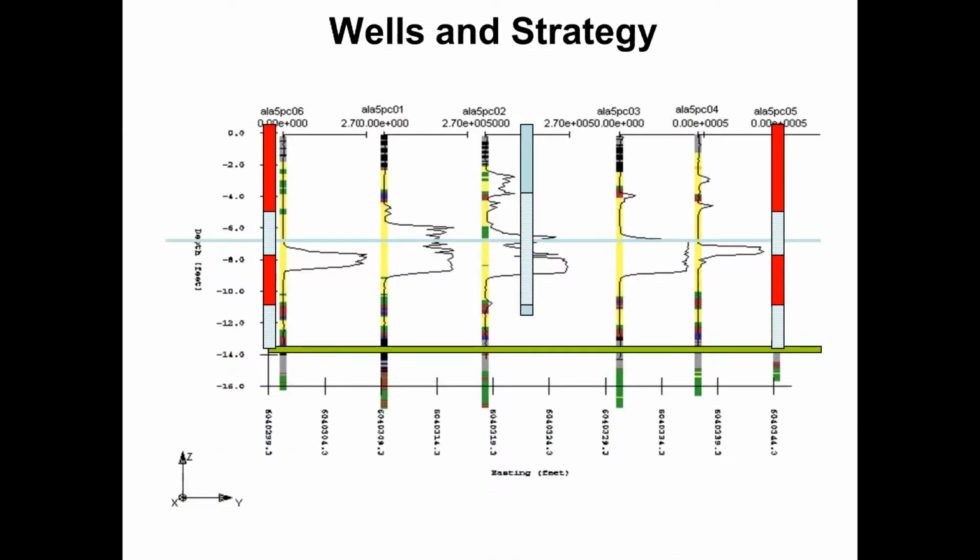That was the approach. And real quick, in a cross section, you see those profiles. Those are laser-induced fluorescence profiles, and they indicate where the hydrocarbon signature was strong when we push down in the middle of the site. You see next to the blue extraction well, there was shallow contamination, and then you reach the water table, and right around the water table and below the water table, really high signals.